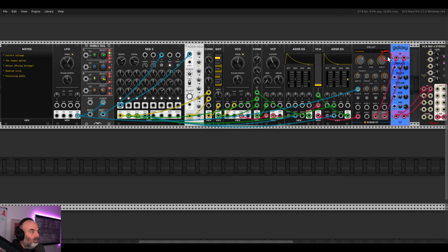Okay, so this was our first voice. Again, we have offset, you can add variation, and create all sorts of different pitch effects, if you will, by offsetting the voltage before the quantizer. In this quantizer, we don't have a CV input for the offset, but we can just mix signals before the quantizer and get the same result.